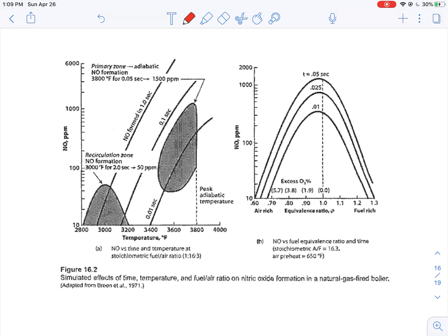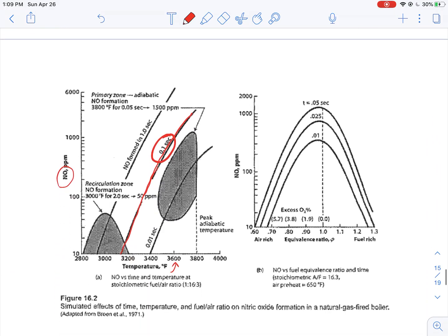So people have also done other studies trying to look at how other parameters might influence the system. This picture here shows the influence of temperature and residence time again. Basically, each curve here represents a certain residence time under high temperature. Residence time just means how long the flue gas stays in the combustion of the coal-fired power plant, right? You can see that for each constant residence time, the higher the temperature, the higher the nitrogen monoxide concentration. This is what we saw from here.